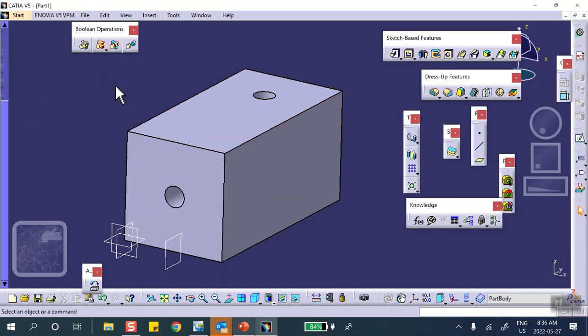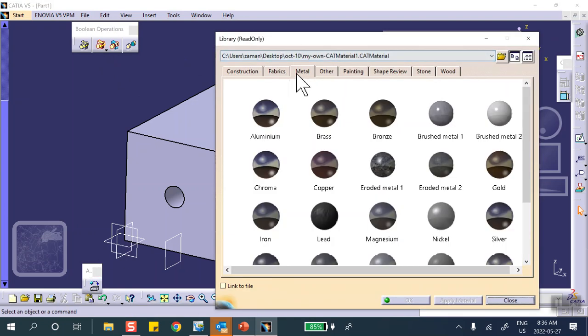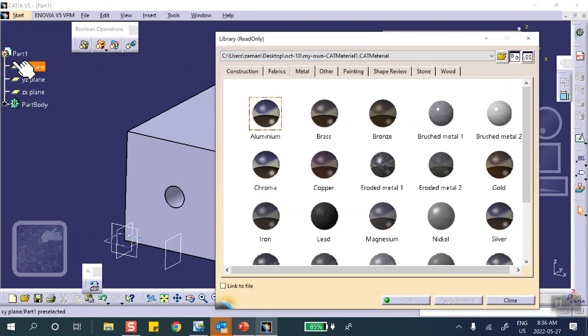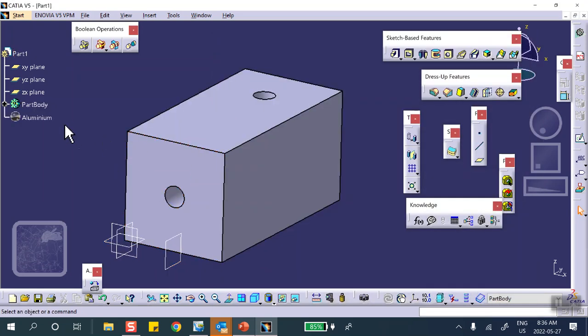So this, let's apply material to this. I think the problem says aluminum. Apply material, aluminum on that part, and we say OK. And let's say extract. You have two choices. You can extract the faces and then cut it, or you can cut it and then extract the faces. That's entirely up to you. So let me actually cut it right now.